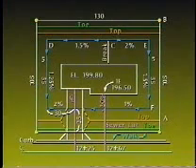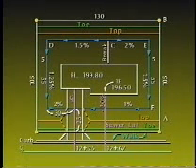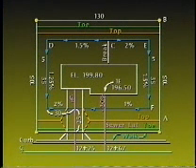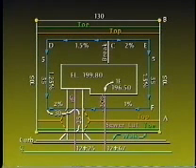We'll do question 2 first, because to do it, we will have to figure elevations at each grade break in the swale needed to solve both questions 3 and 5. We begin with the elevation we obtained in question 1 at the back of the walk and the center line of the driveway. Dimension and grade from this point to the swale grade break in the driveway is given, so we can calculate an elevation at the swale grade break at the center of the drive.